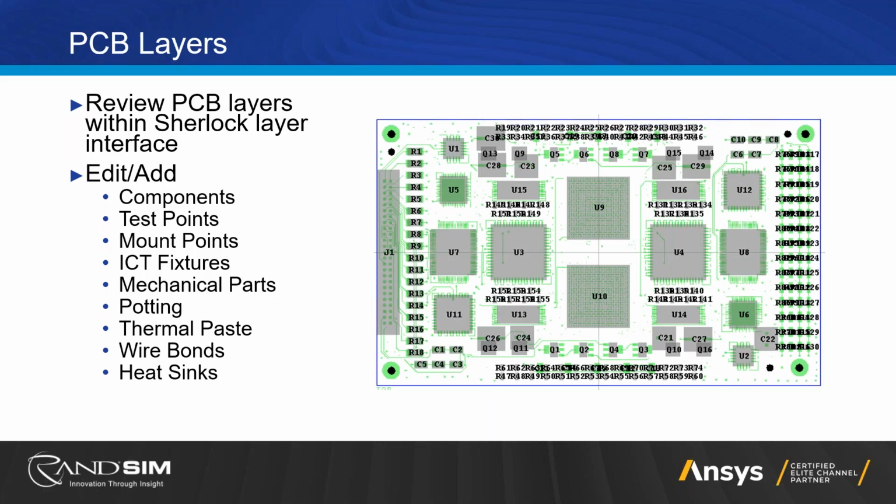What the ODB++ includes is the components, your test points, and your mounting points. The locations of your test fixture points are not necessarily in the ODB++, but you can assign where you put them.